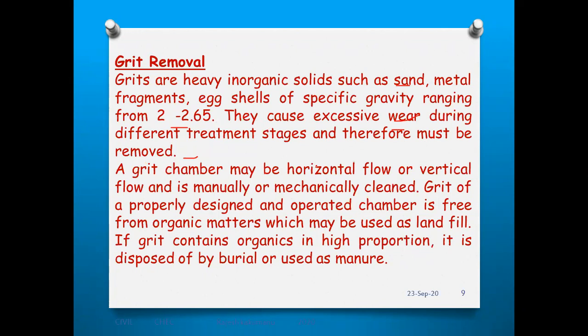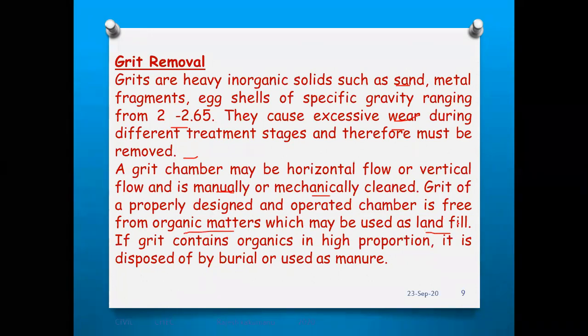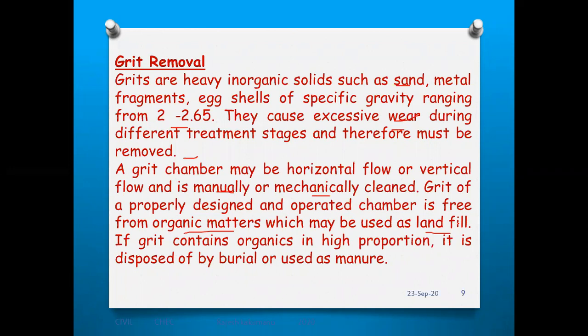Next, a grit chamber may be horizontal type or vertical type, which is manually operated or mechanically operated. The grit of a properly designed and operated chamber is free from organic matter and may be used as landfill. So whatever material is coming from the grit chamber waste, only the organic matter is used for the landfill. Inorganic matter should be dumped in burial places or dumped and covered with soil.